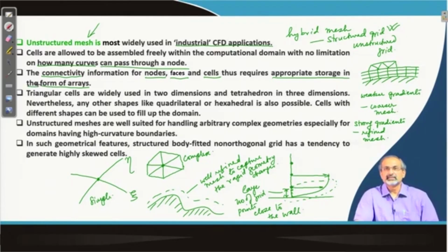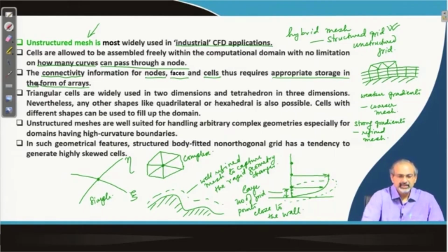Sometimes we will see that in certain fluid dynamic problems, the mesh also needs to change with time. So, if you are having such a scenario, the mesh also gets enormously deformed because there may be a moving boundary, and the way the boundary moves may necessitate addition of cells in some region of the flow and deletion of cells from some other region of the flow. In that case, the connectivity information has to be rebuilt based on how the mesh is evolving.